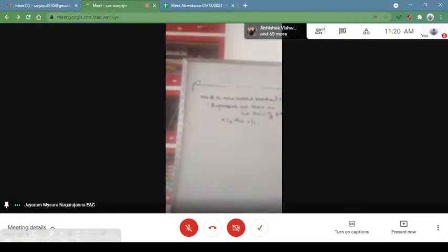M equals 0 means no peak, no zero crossings. N equals 1, one peak or one zero crossing. M equals 1, N equals 1 means there will be one zero crossing, one peak. Like that, they tell about the orientation of the electric and magnetic field across the cross section of the waveguide system. And here we come across an important terminology called the dominant mode.